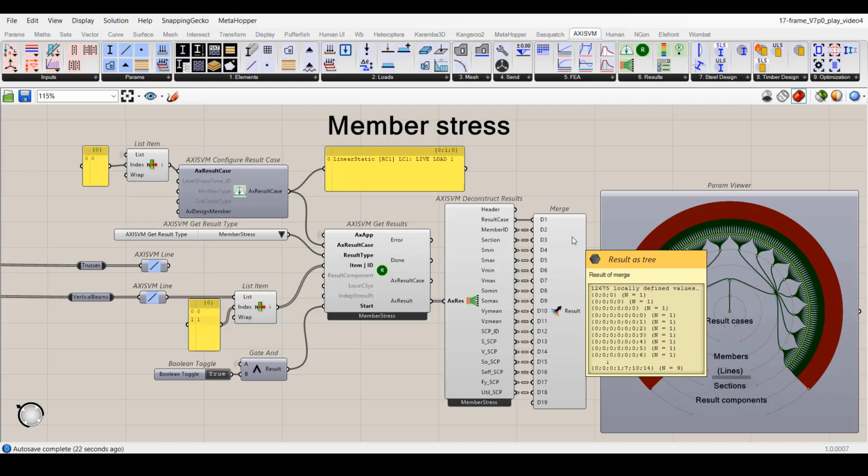You can see that I don't have any branch path with 5 indices, but the 5th index of the section paths is growing from 0 to 7 to group the sections according to the finite element mesh. Last but not least, I mentioned that similar data structure is used, of course, for line stresses as well.